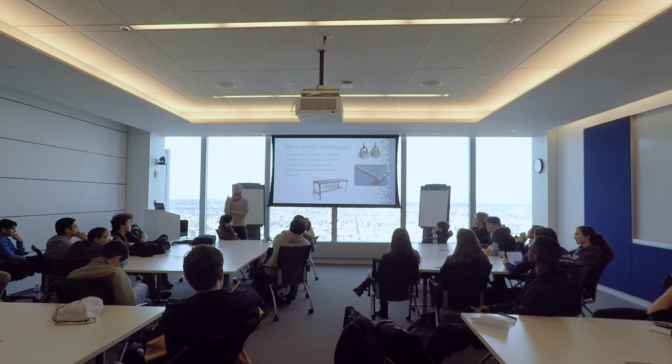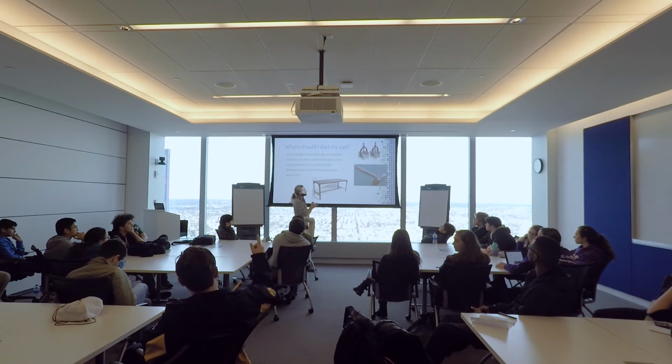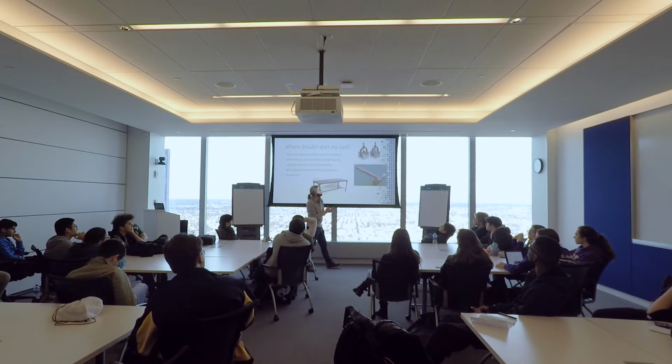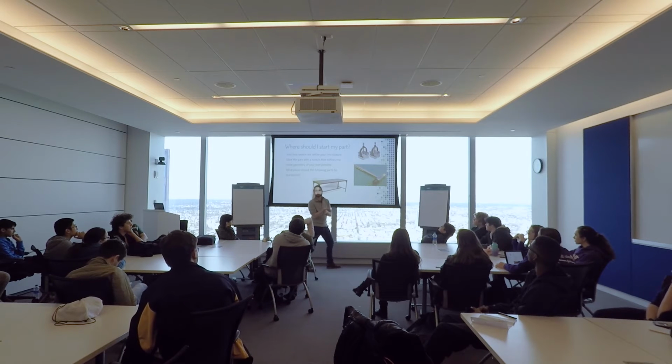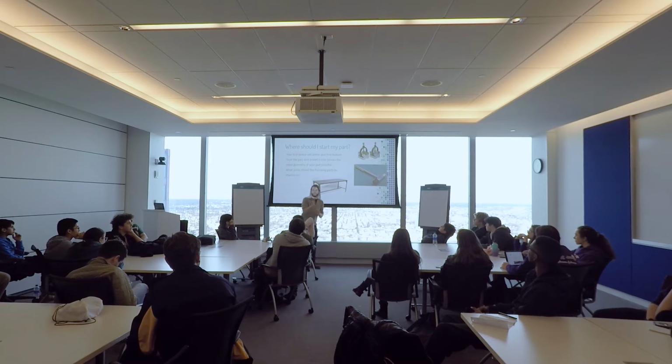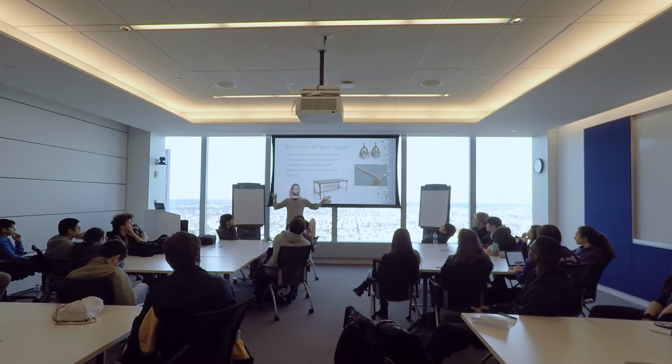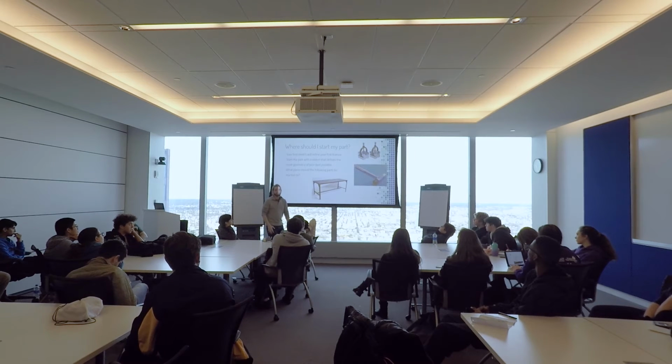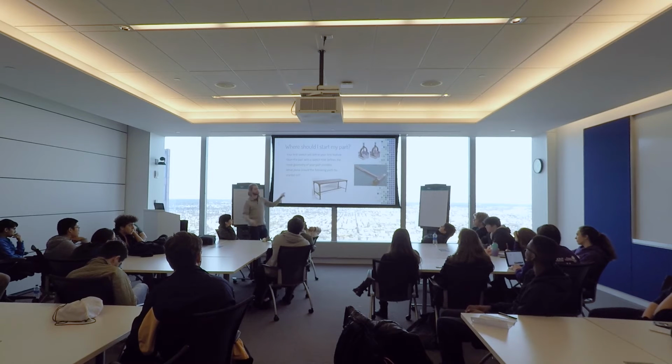These are the kind of things you have to think about. It depends on what's in the center. I can't see the entire geometry of the thing. But generally, you want to have your part centered on the origin, right? So you would want to do a mid-plane. Mid-plane just means it extrudes the same amount one direction as it does the other direction, and the total width of the part is that extrusion. So I would definitely do a mid-plane extrusion on the front plane, as you said.